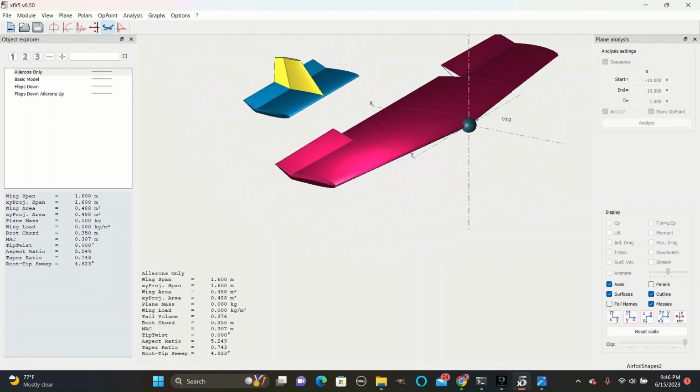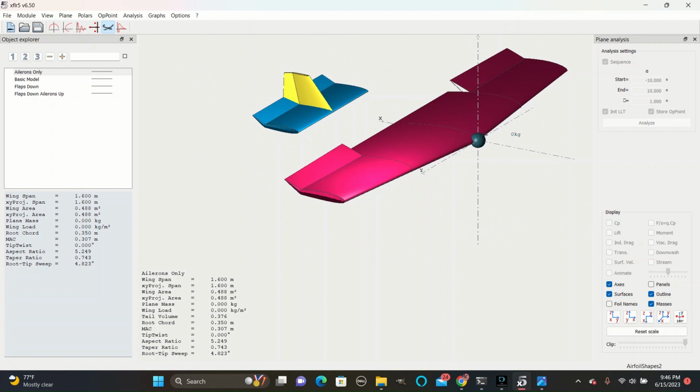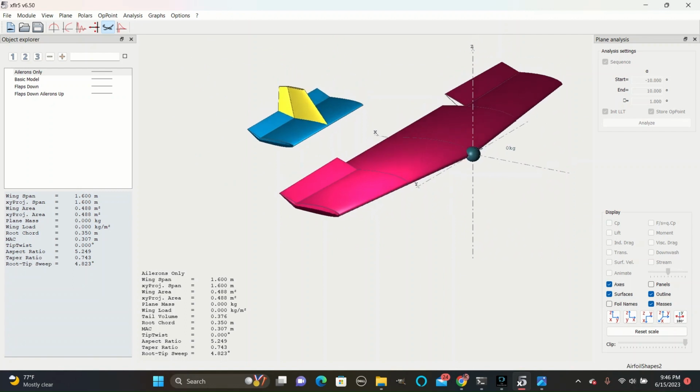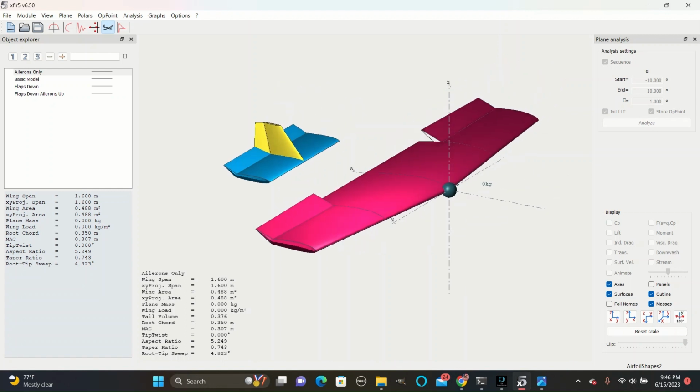The aileron is the control mechanism at the tip of the wing that allows the rear part of the wing to rotate up and down like a flap, and is primarily used for turning. You can see them pictured pointed up in this design. The angle of attack, abbreviated AOA, is the angle of the plane, though more specifically the wings, relative to the motion of the air. This is equal to the velocity of the plane if there is no wind. However, if there is wind, that must be added to the plane's velocity to determine AOA.